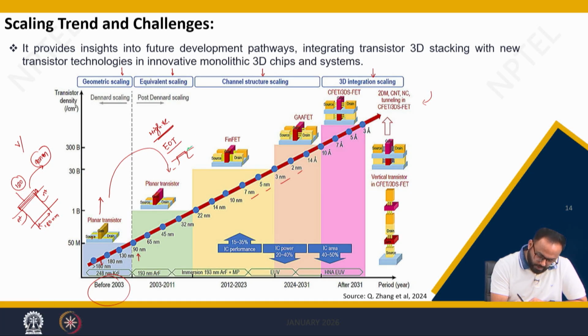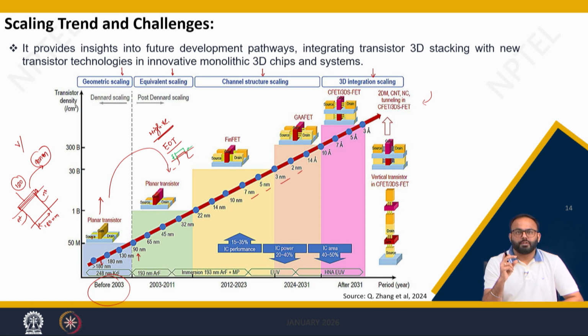So, this is silicon dioxide over which you stack a high K dielectric, such that the effective oxide thickness over the MOSFET will increase. So, this is the era when we were discussing advancements in planar MOSFET, like strained silicon, silicon germanium, EOT, high K dielectric.